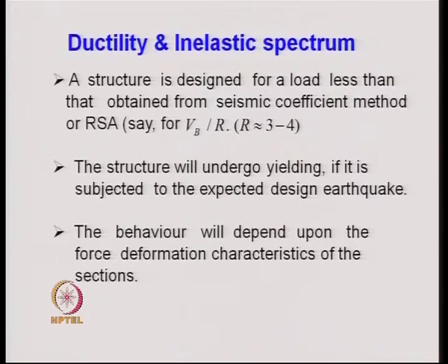Because of this reduction factor, a reduced load is acting on the structure, and we analyze the structures for that reduced load. As a result of that, in the case of the actual earthquake, all the structures that we design undergo inelastic excursion, that is, it goes beyond the yield limit.